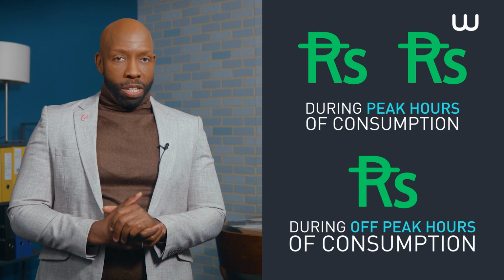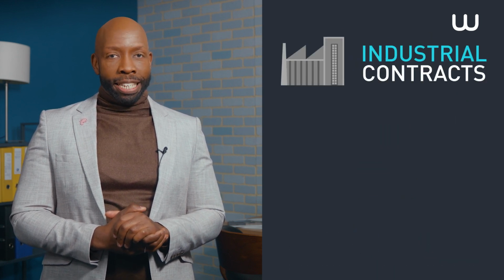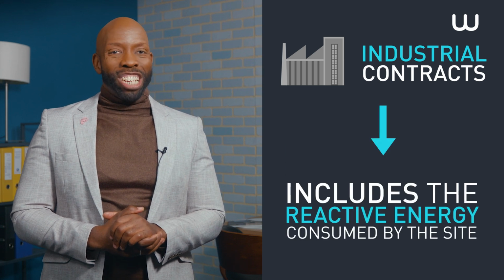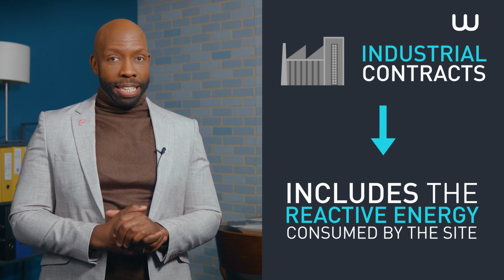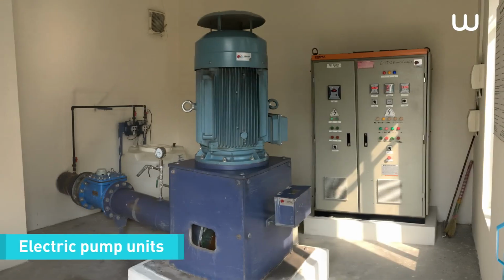For industrial contracts, which are often connected to medium and high voltage networks, the variable charge of the electricity bill also includes the reactive energy consumed by the site. This is the case for many sites operated by a water utility. Reactive energy is the energy used by magnetic circuits in electric machinery with induction motors, such as electric pump units, to create their own electromagnetic fields.